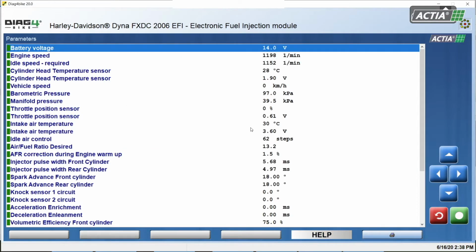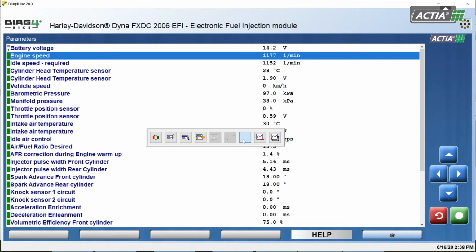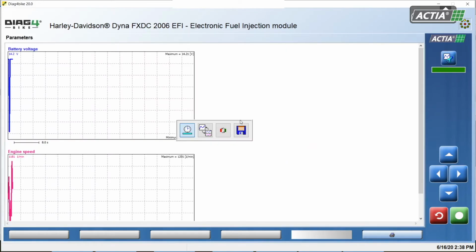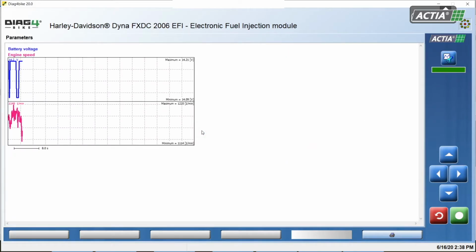Parameters can also be easily sorted and ordered as needed. You can also view up to 4 selected parameters synchronously in the form of a chart with an adjustable time axis. Proper choice of parameters allows performing a number of diagnostic operations. To illustrate, you can chart the parameters of the charging regulator while also displaying the speed characteristics of the engine with speed ramping up from idle, while also measuring the voltage in the accumulator.